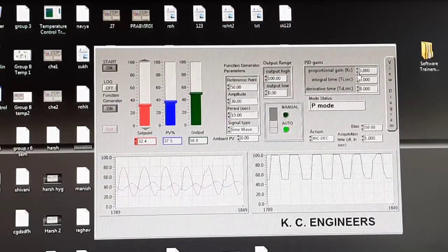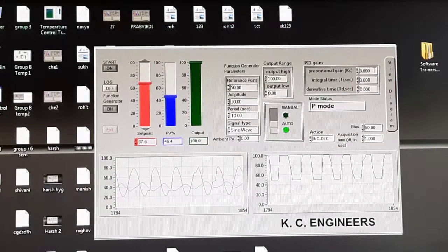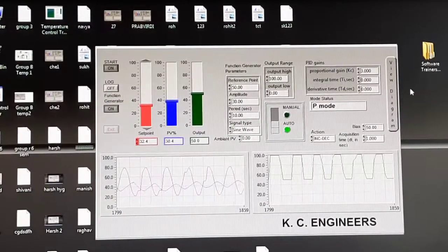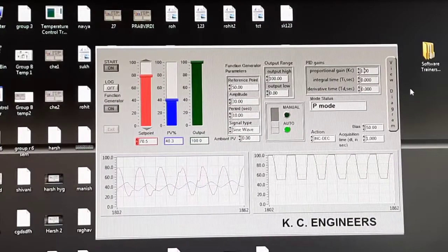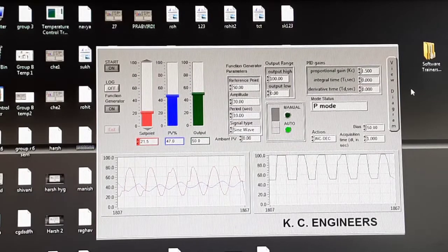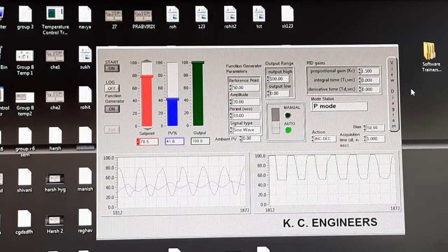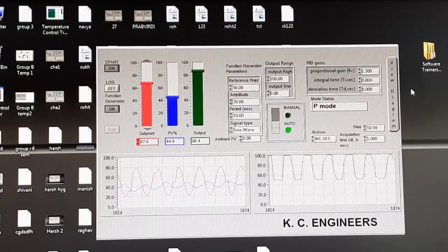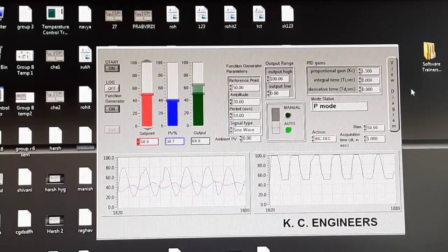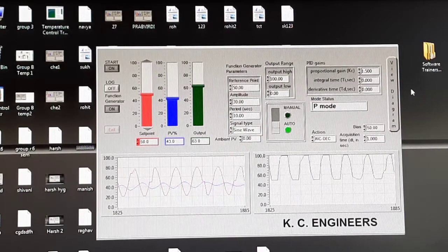Let us see whether we are getting a smaller number or not. I will make the Kc value 1.5. You will observe how the curve is changing. The smoothness has increased now, if you observe, but the magnitude is decreased. The peak magnitude is decreased, but smoothness is increased.